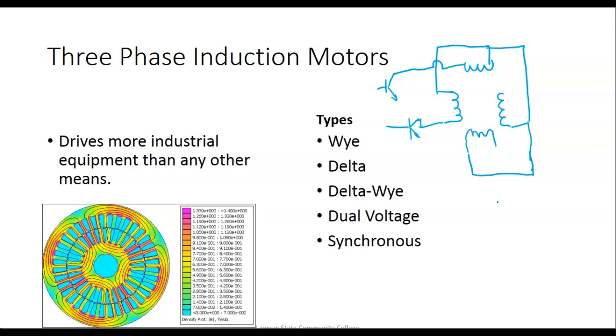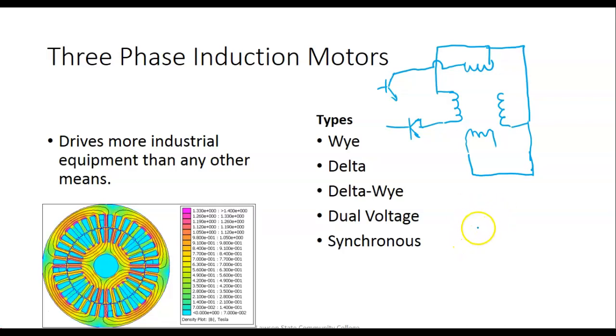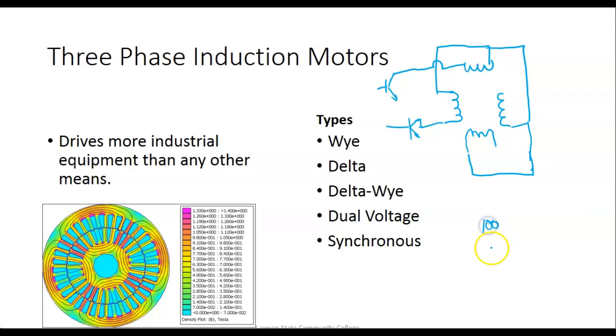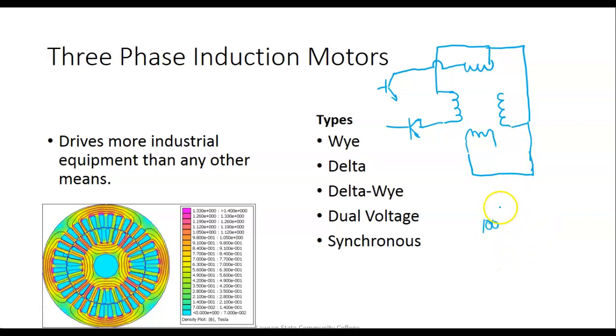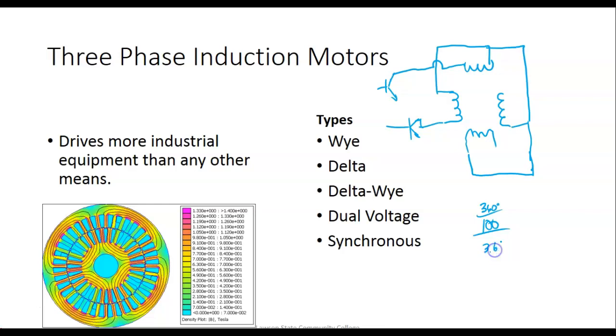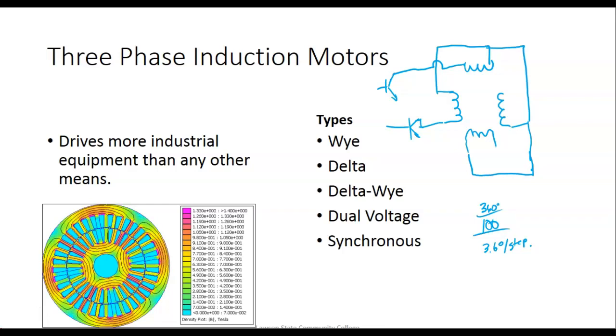I've got a stepping motor circuit hooked up, but I can't find my program that runs the Arduino. What's nice about a stepping motor is it moves in steps. Our stepping motor has 100 steps, and you can actually feel them, guys. In 360 degrees, that means we would get 3.6 degrees per step. This is accurate. And so you can actually see it on the module 3. That's the motor that it's running.